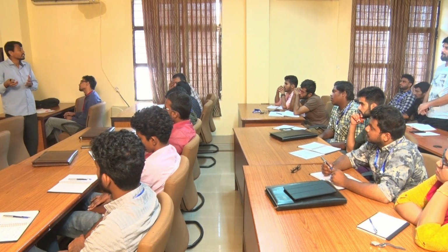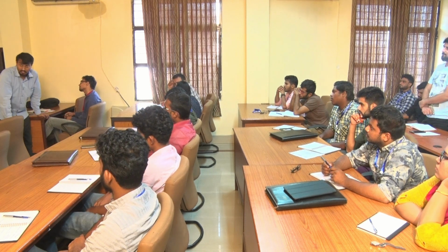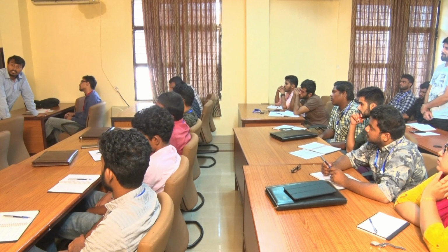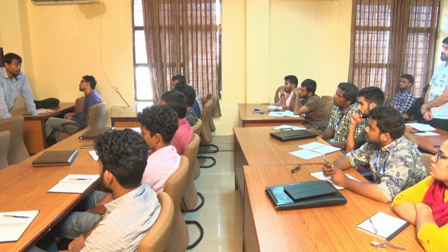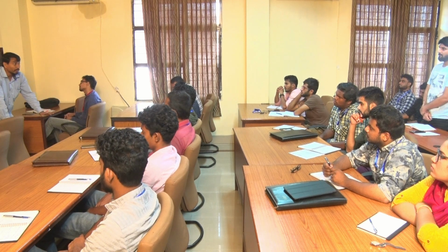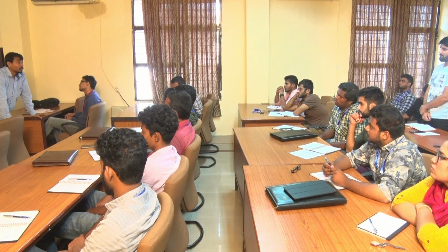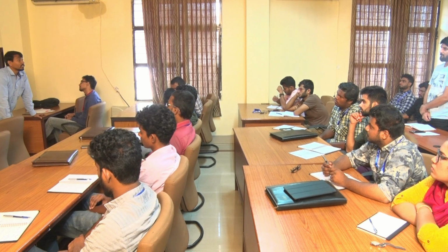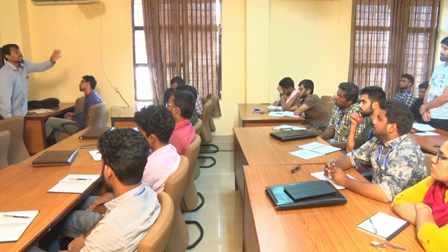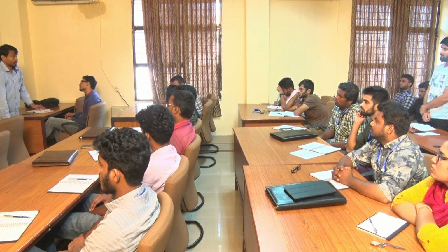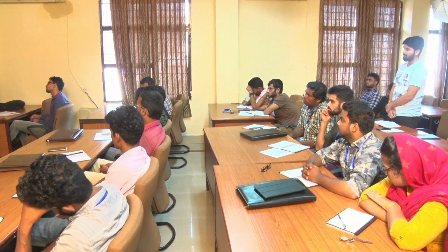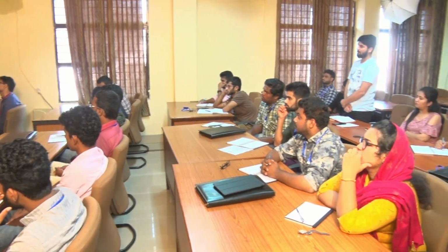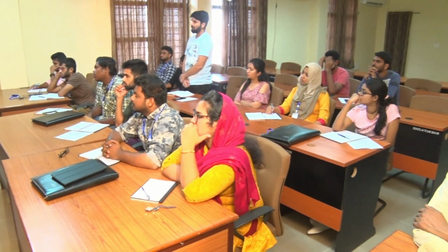They suggest if the joint orientation is favorably oriented, your RMR may be good, whatever you have calculated. But if the joint orientation is not favorable, then you need to apply a correction factor, and these are the correction factors proposed. These correction factors are by magnitude all negative, meaning whatever RMR is coming, the modified RMR is that minus that.